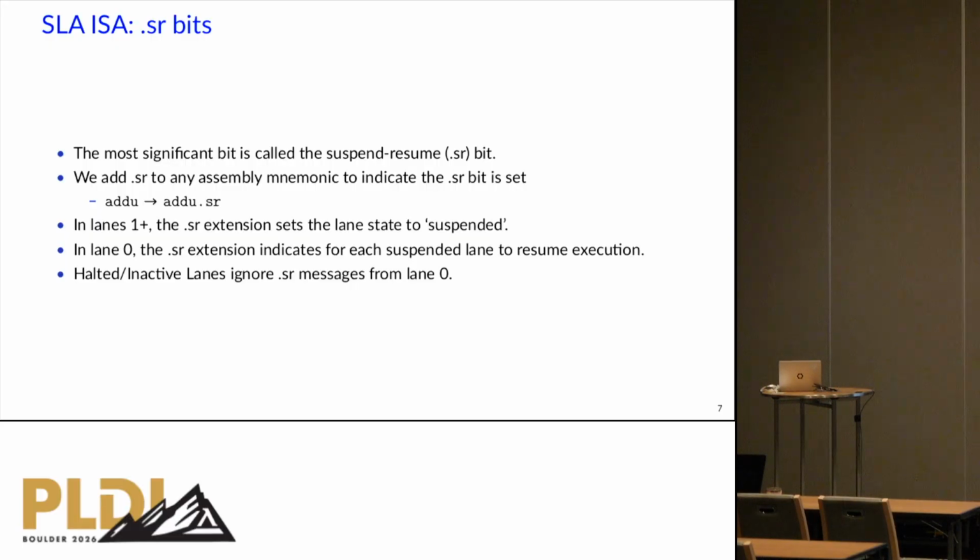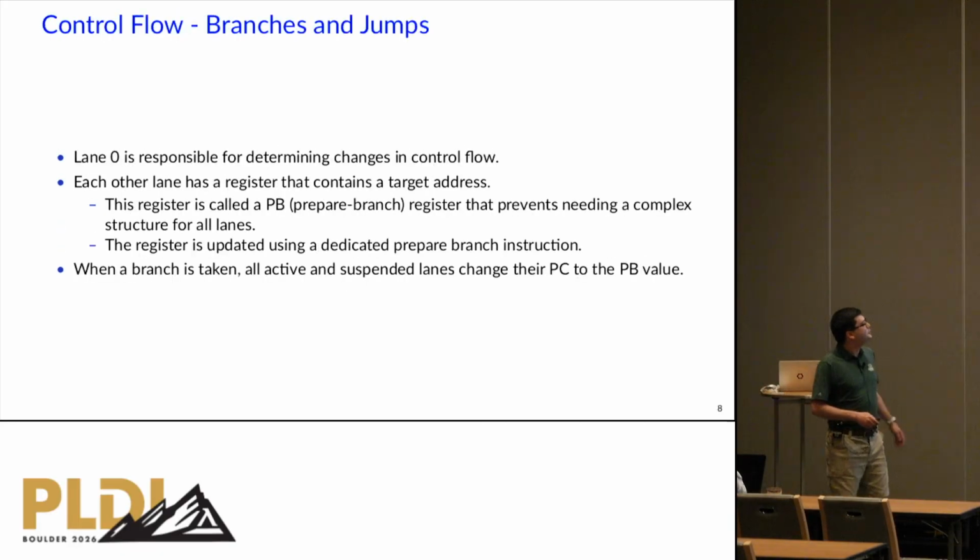Lane 0 has a .sr extension, but since it can't turn off, all it says is all other lanes that are currently suspended but still have a PC, resume execution. Halted and inactive lanes do not have a PC, so they won't continue. So that's the basic idea of these SR bits.